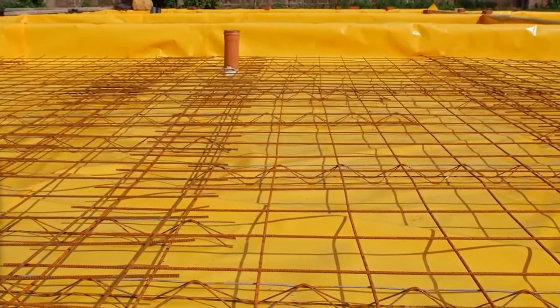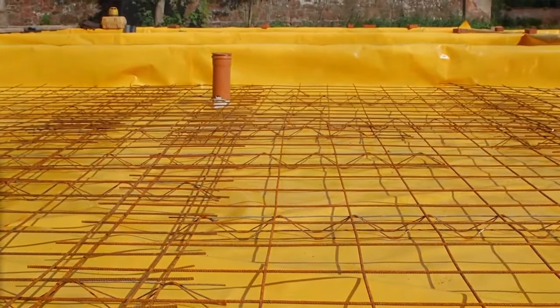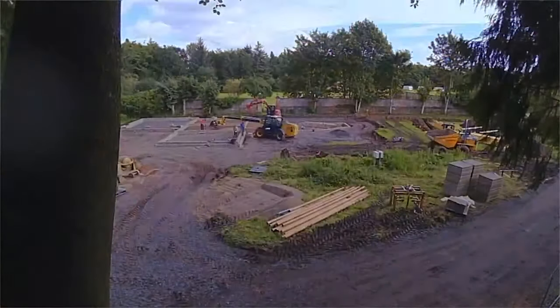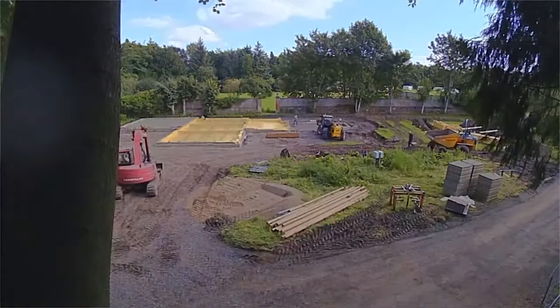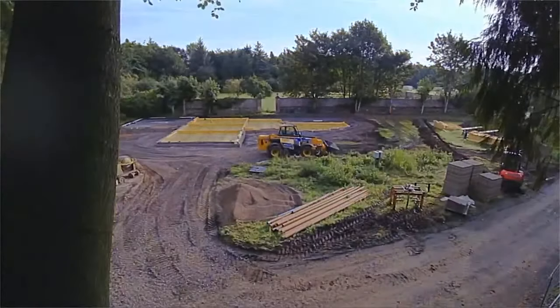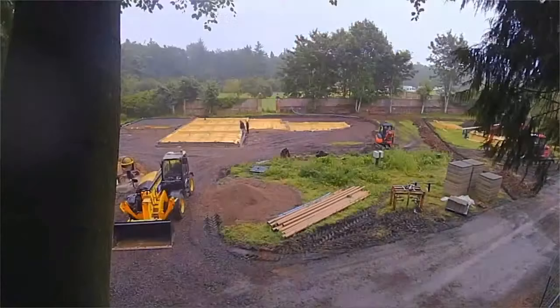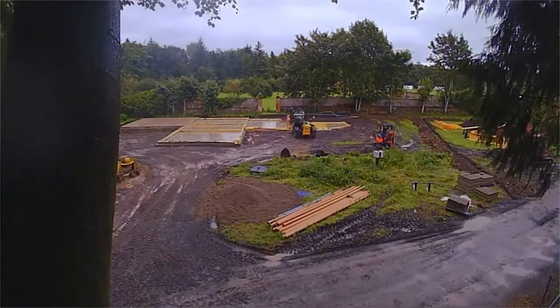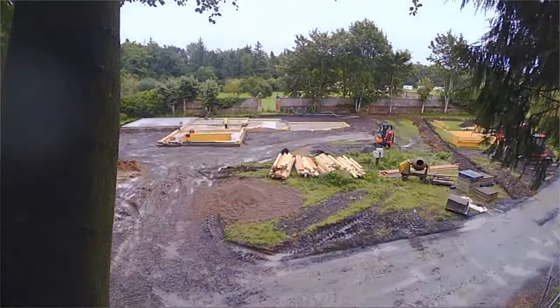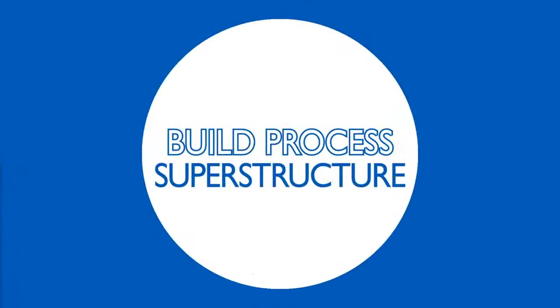And whilst we used the Proctor membrane, which was an overspecification, this wouldn't have normally been required for my particular site. Here, the floor slab is poured on top of this membrane, and this type of foundation is known as a ground-bearing in situ slab, as the slab is fully in contact with the ground and is poured into place directly. Which type of foundation is used is determined by a range of factors, such as geology and the loadings from the building itself, the construction of which we'll look at now.